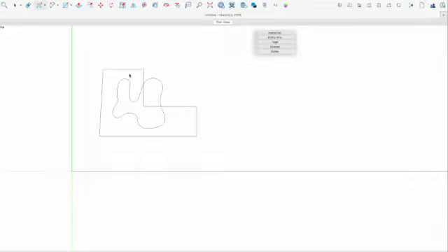Next, we can try out the rectangle tool. It will draw a rectangle if you click and then drag to the opposite corner. If you look at the measurements box at the bottom of your screen, it is showing you the length and width of the rectangle you're drawing in real time. The rectangle tool also has a drop-down menu, so we can choose circle next and draw a couple of those. It draws from the center, and you can tell it what radius you would like in the box at the bottom of the screen. We'll get more detailed with these things in the coming weeks.